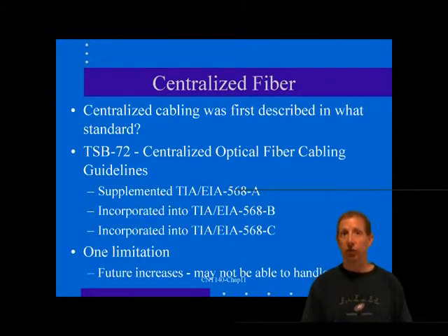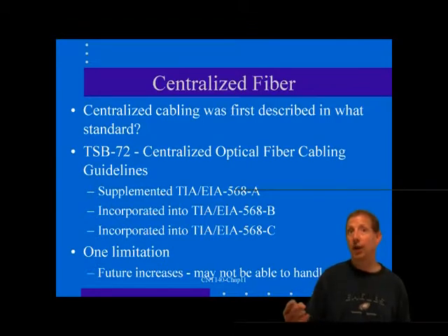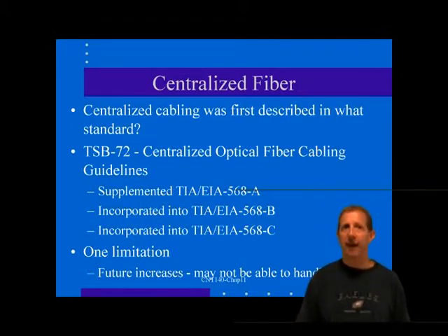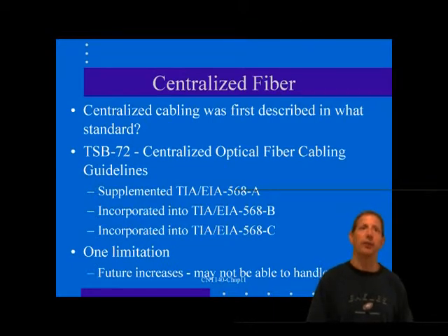As with the structured system, you may use multi-user outlet consolidation in open offices, as stated before. All fiber systems are inherently interconnect systems rather than cross-connect systems. From a practical standpoint, it matters not where the interconnection occurs, so the MUTOA takes the place of an interconnect in a TR in the centralized fiber layout. Centralized fiber cabling is a viable option for any fiber cable installation.